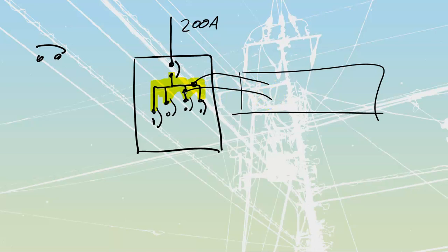You need to have a separate overcurrent device that runs off of it from here into that splitter. So it's going to be protected through this breaker right over here into that actual splitter that we're going to have.